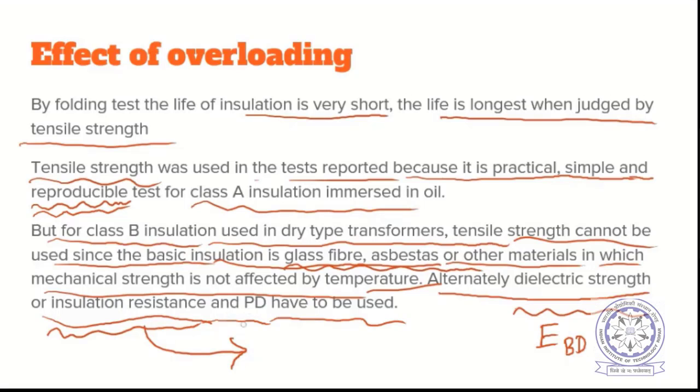And the third one is partial discharges. This is another aspect. Within solid insulation, there may always be some voids. Voids means air gaps, or gaps filled with some gas during the manufacturing of the equipment, such as epoxy, glass fiber or asbestos materials.